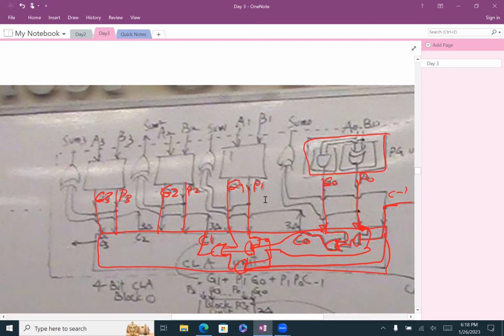All right, so how much is the delay we said here? Total? 3 delta up to here, correct? However, here it's 4 delta. Okay, for the sum, it's 4 delta. Now, can I use this circuit to make a 16-bit adder? Yes. So what do I have to do?